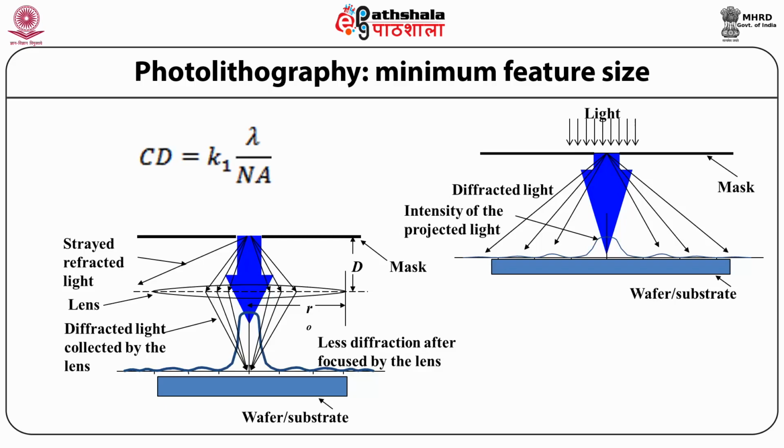So, students, in photolithography, the ability to project a highly resolved image of a small feature onto the wafer or any substrate is limited by the wavelength of the light used for photolithography and the ability of the reduction lens system to collect the maximum number of diffraction orders from the prefabricated illuminated mask.